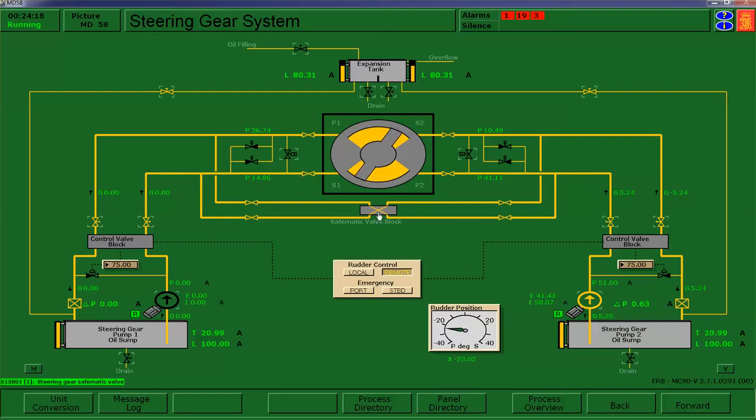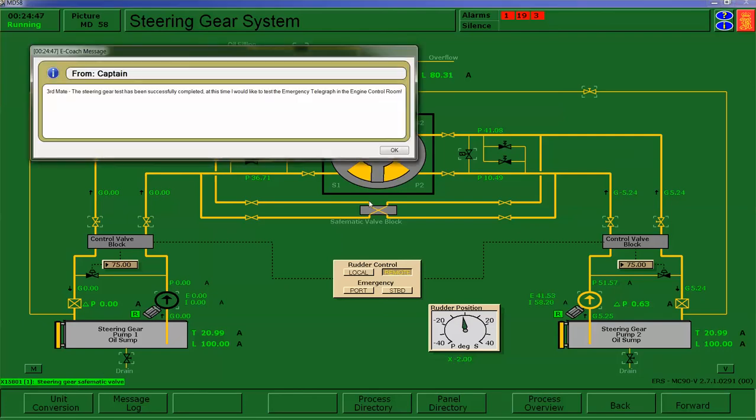Then what happens is the Safematic, this valve block, would open and then automatically open the bypass on the other side. On, like, say, this running this unit, this bypass would open and the Safematic would open, so that if the oil leak was on this side, it wouldn't drain the other unit. And this is required by international law now. So if your expansion tank level drains down to a certain point, the Safematic block would shift to prevent you from draining all the oil out of the system.